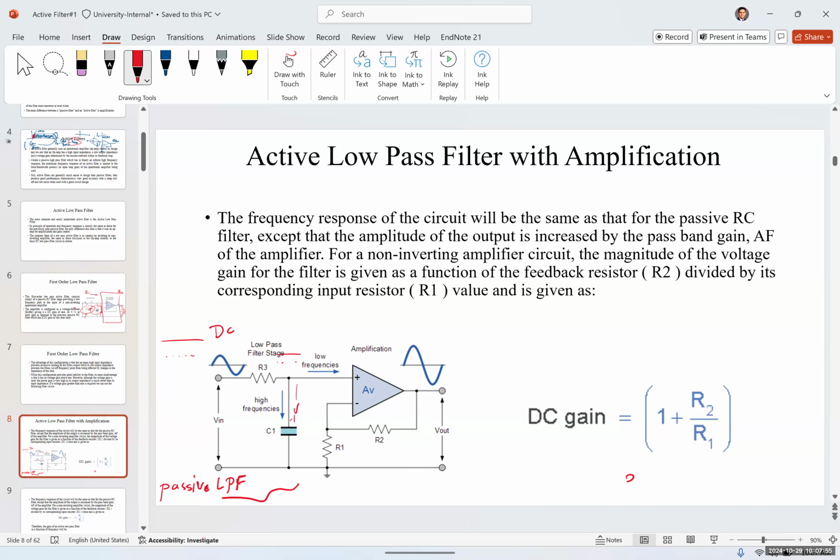Now this DC is going to charge the capacitor, yes? When the capacitor is fully charged, what happens to it? It becomes an open circuit. Again, the same analogy that I showed you. A capacitor, when you have a DC, is going to be blocked because it's going to fully charge. So now imagine we don't have even that capacitor because it's going to get charged in the first few milliseconds or microseconds, depending on how big the capacitor is.